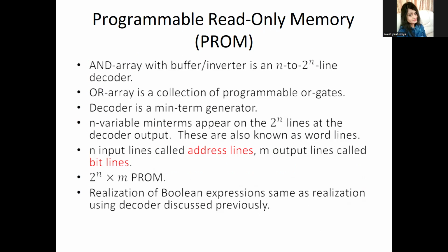Now let us discuss the programmable read-only memory, that is PROM. PROM is the simplest form of PLD. It contains a fixed decoder for addressing and a programmable OR array that stores the output logic. Each input combination selects a specific memory word that determines the output.